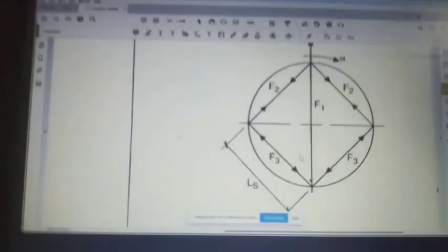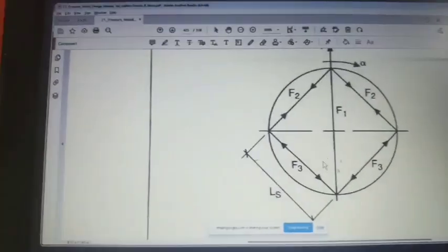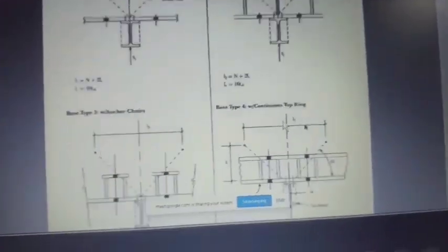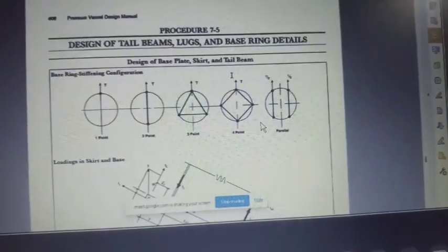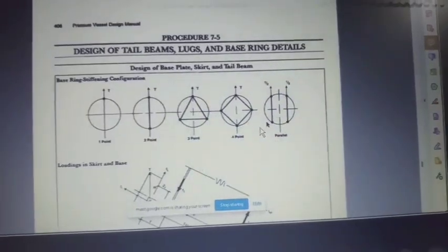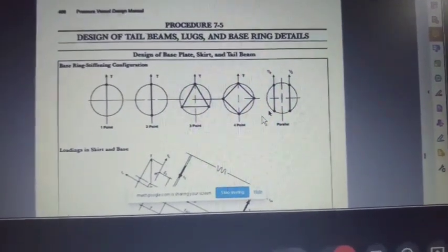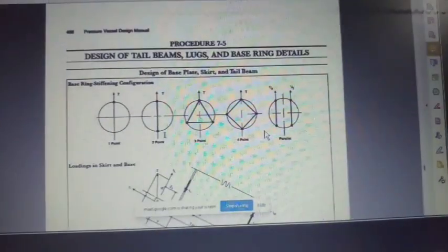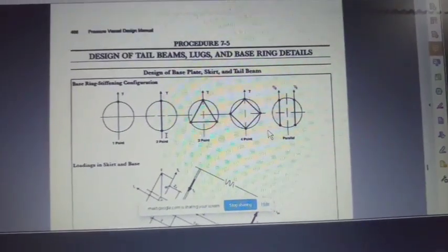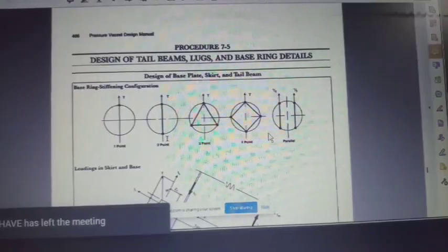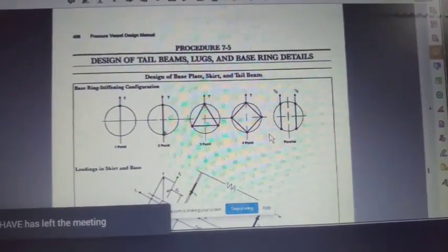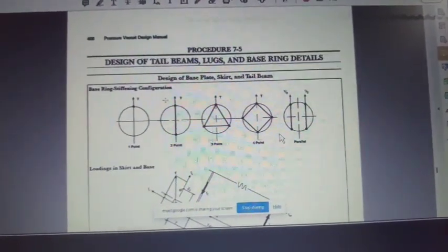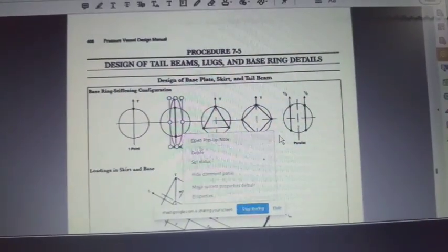For a vessel, I am designing a lifting beam. Normally, I use this configuration. With this lifting it is not passing, so I need to go for 4-point lifting. This is the figure we are referring to. My question is, when Dennis Moss shows the sketch here, it is not showing anything here, but when it comes to here, it is showing this point. It means that along with these 4 struts, we need to give the central beam also. That is the question.